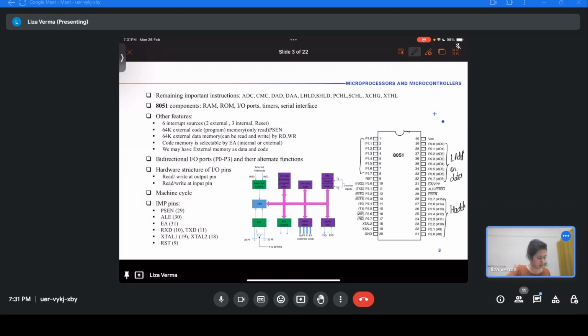I don't think it will be the 0006 memory location. Push operation is done using a register pair, ma'am. So the address will be decremented by 2, and the stack pointer will be pointing two address locations lower. That's for the processor, it's okay, but is it applicable for the controller also? I have a confusion there. What am I missing? Just a minute.